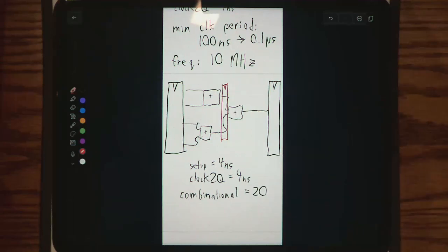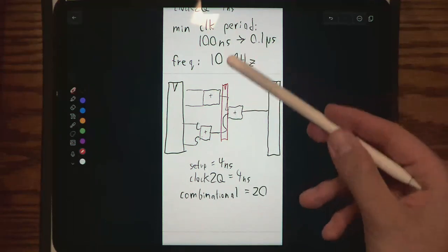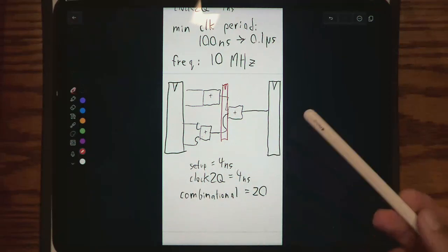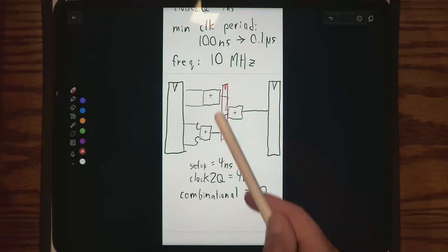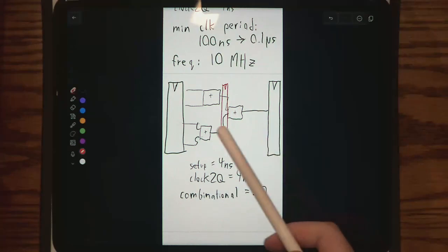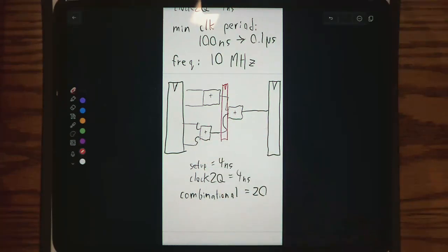Looks like it'll overall slow down your design by at least like 8 nanoseconds, if not more. So yeah, it's not perfect. If you're wanting it to be as fast as possible, there technically are faster ways that you can do this. But this is definitely the most popular way of brute force speeding up your clock frequency: add a pipeline stage.